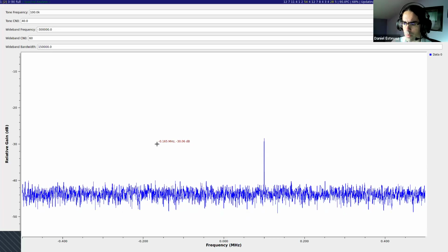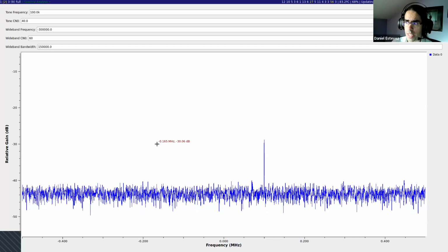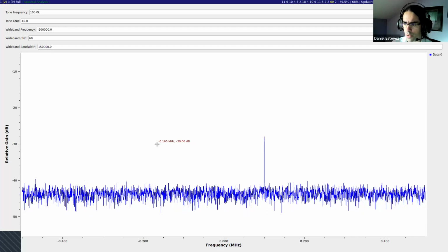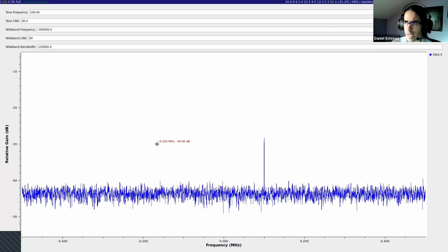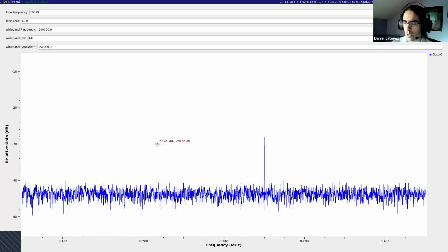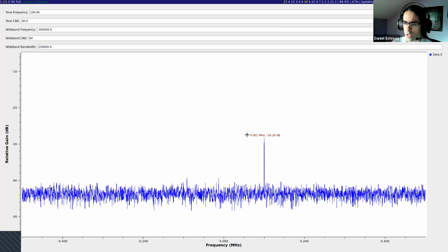And that would be a fine way to measure noise power. But then you need to remember when you are communicating this to another person or in some document, you need to say, I'm measuring the noise at 1 megahertz bandwidth because that person might have done manipulations with the signal.